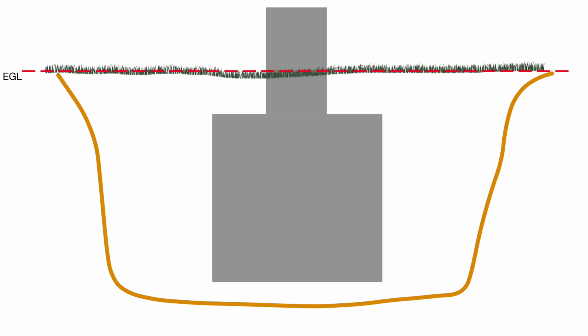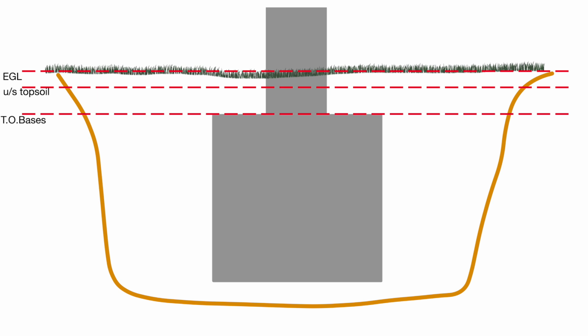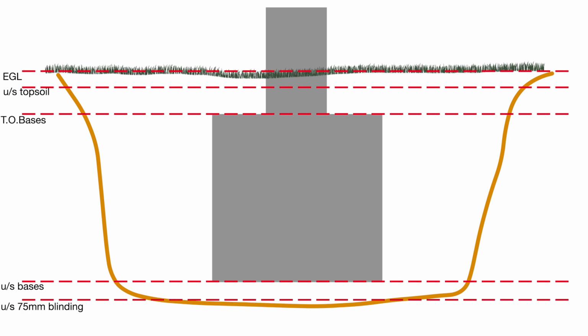This sketch shows a typical base and column in an excavation. From a measurement perspective, we measure topsoil removal first and assume 150mm, as it's impossible to be super accurate. This is Class D, general excavation topsoil. Next, we have excavation from the underside of topsoil to the top of the bases. So we have again general excavation material other than topsoil because it's overall the site. Then we come to the actual individual base foundation excavations from top of base level to the underside of bases, plus the additional depth of 75mm for the blinding.